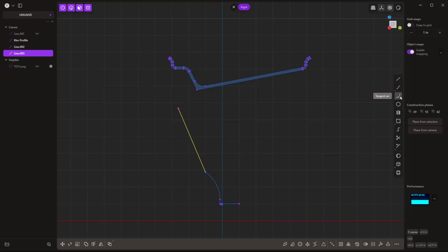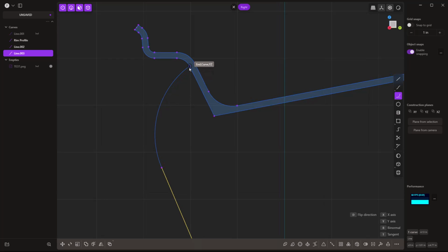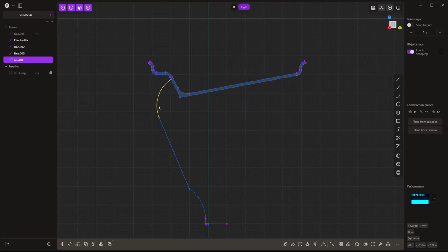So left click, then we'll go to our tangent arc. So from here, I don't want to snap to this point. I want it to come back a little bit. When you look at a TE37, you actually end up seeing that there is a large fillet that blends this corner between the spoke and the rest of the rim. And if you put it all the way into the corner or you match some other geometry, oftentimes it's not going to give you the result that you need. So I just like it to end a little bit short, and that'll help with that transition.